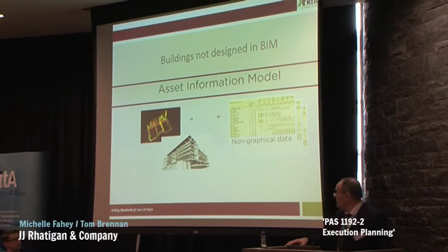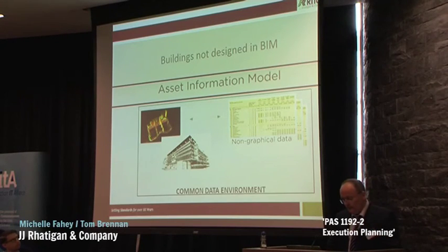So then we look at buildings that are not designed in BIM. What can be done here is that we can prepare a BEP, we can carry out a 3D laser scan or a point cloud, and from that we can produce a BIM model. And from that BIM model we can input information which is COBie compliant, and then we can use this for facilities management such as planned and preventative maintenance. All this is done in a common data environment.